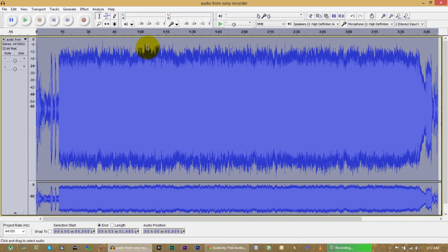Okay, that's good. It goes back to what I said, that it's better to drop stuff out than to increase. If you ever apply equalization and your overall waveform increases a little bit, then take every part of your curve, every one of your bands, and drop them all a decibel or two, and that keeps it from having an overall increase in amplitude at any given point.